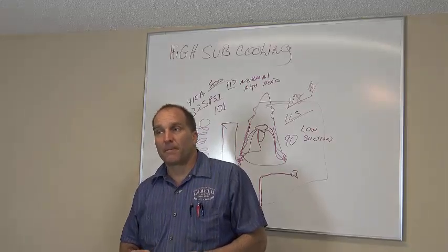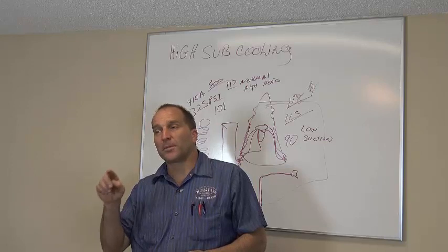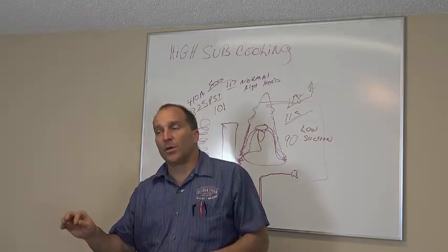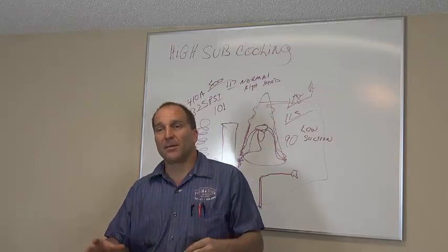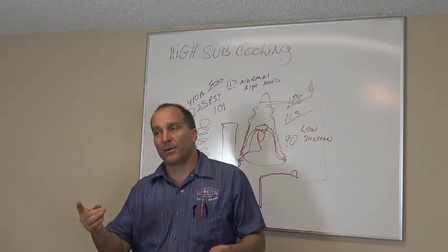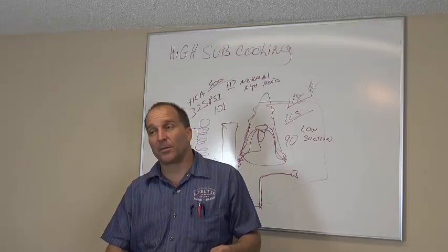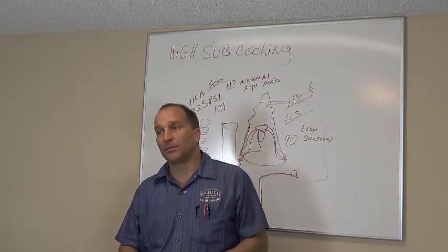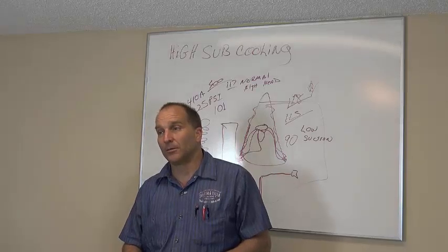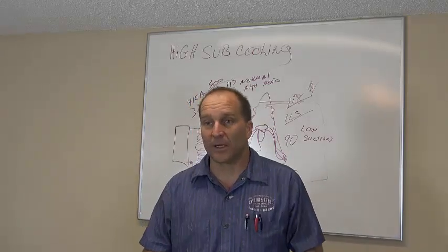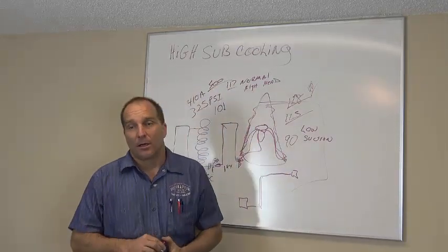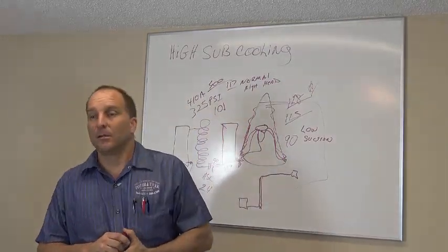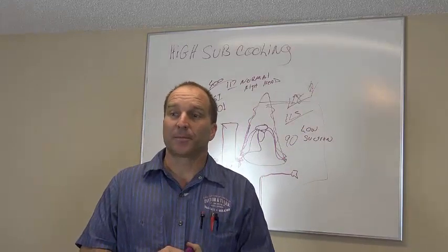That's restricting airflow, which drops your suction pressure, which drops your head pressure. The dropping of pressures and temperature makes the refrigerant coming through the system colder, so it actually does affect your subcooling, making your subcooling cooler, which is higher. So high subcooling could be affected by low superheats.